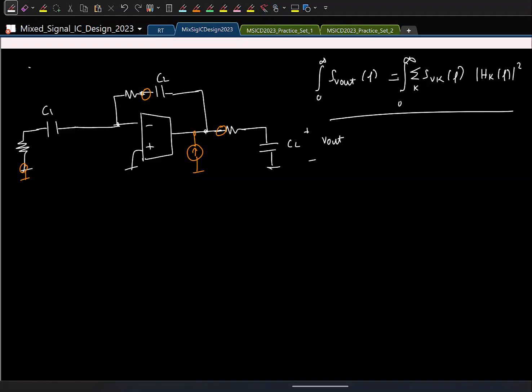So we'll do a gross approximation. We already saw that the on resistor is going to be much smaller than 1 by gm, right? So I'll ignore that. Majorly noise is coming only due to gm, and the noise due to on resistance can be neglected. Okay, so that is going to simplify my things. I'll ignore all on resistance. This is a gross simplification, but just to get a feel for how calculations can be done, we'll do that. We'll only consider noise from the OTA.